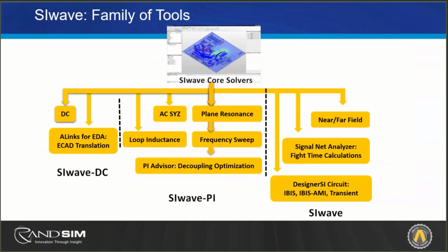This is again increasing the strength of the tools, and one I don't have listed here that incorporates IBIS models is looking at DDR for compliance. So we design, we have what is given to us by the manufacturer for information related to DDR, and we want to ensure that our PCB is meeting the specifications set by the manufacturers.